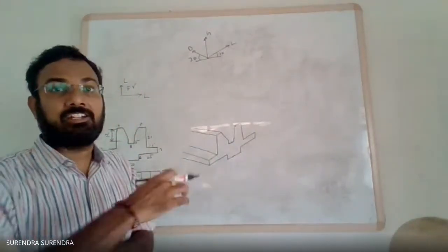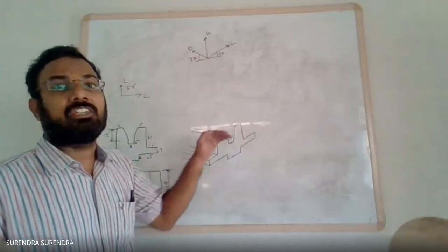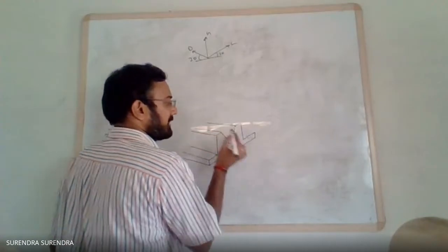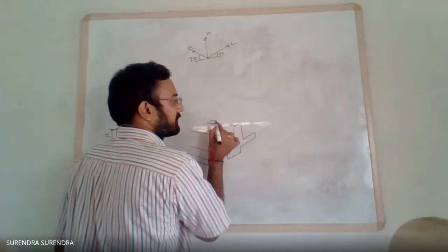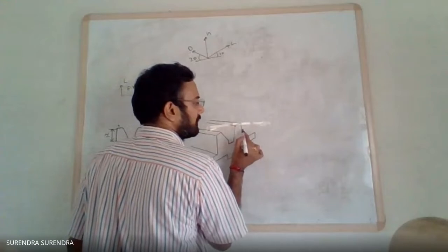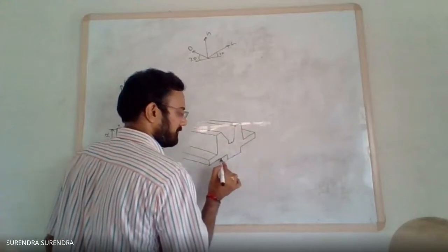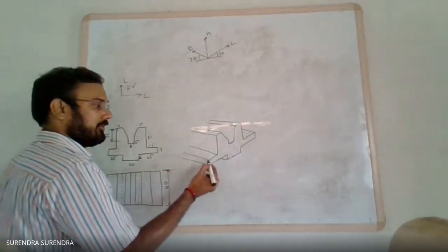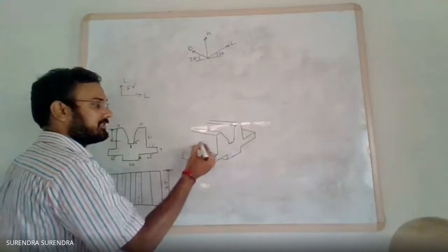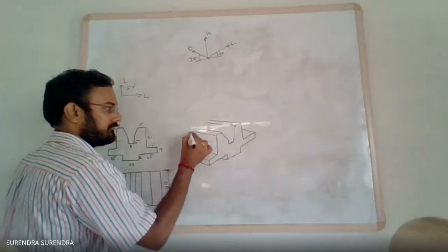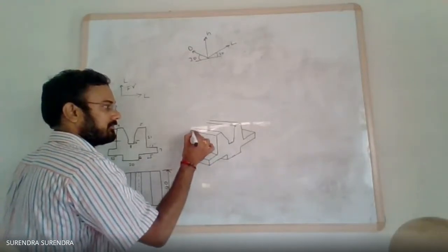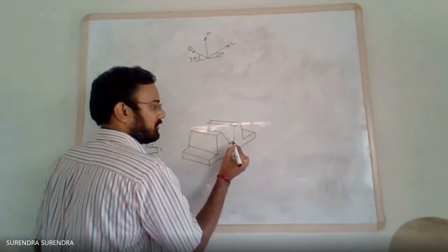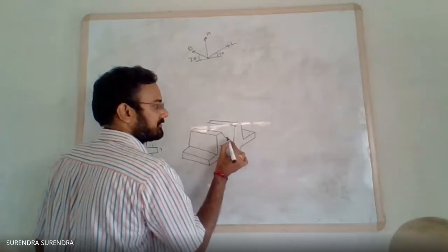If you fix the drafter at 30 degrees and draw, it becomes easy. The best way for this is using the drafter. Then join the upper corners with vertical lines as they are. From these corners also draw 30 degrees inclined lines.